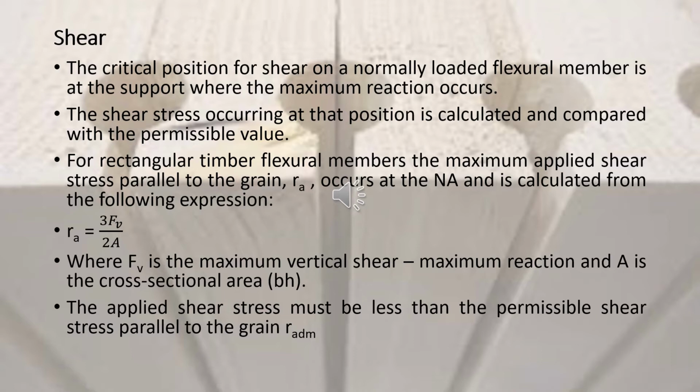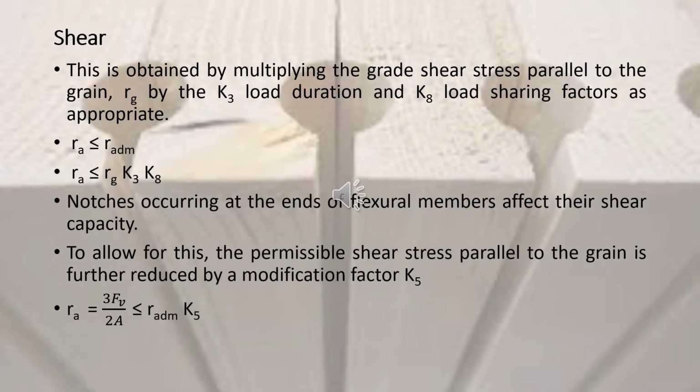All right, so this is about the shear. Now, the shear stress parallel to grain should be less than or equal to the permissible shear stress parallel to grain.